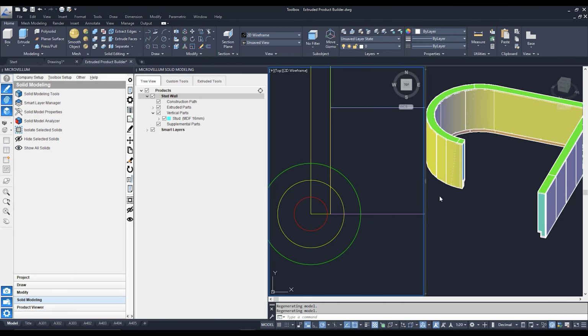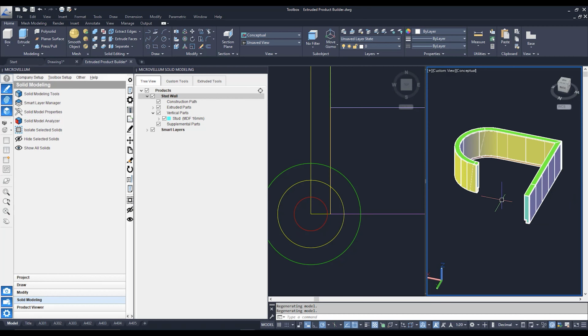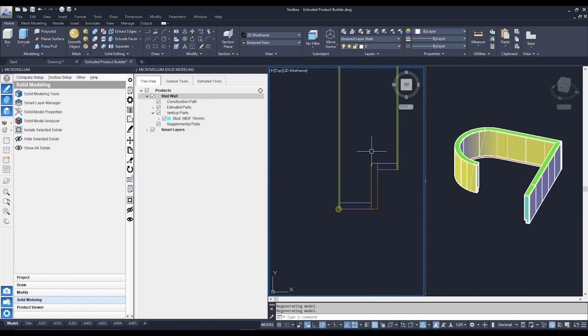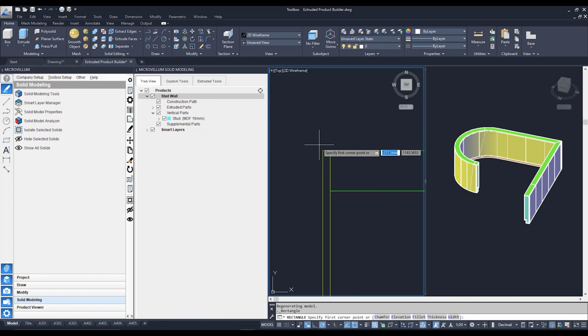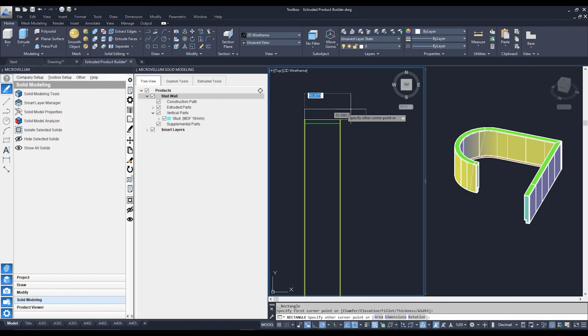Now, there's a few things that we can do to edit this. We can obviously adjust things like where our studs are coming in, where our extrusions are ending and starting. We can also add further parts to this entity over here. I actually forgot to add a bench top to this. So we're going to add a bench top simply by adding in a rectangle and adding that to our 3D. So again, blue pen, again, rectangle, and I'm going to click on this point over here, and I'm going to make this guy over here about 350 in length. I'm going to make him 25 mil.